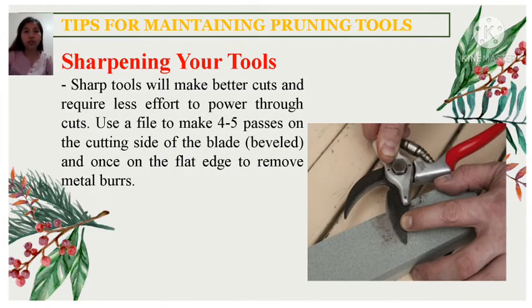For sharpening tools, sharp tools will make better cuts and require less effort to power through cuts. Use a file to make 4 to 5 passes on the cutting side of the blade and once on the flat edge to remove metal burrs.